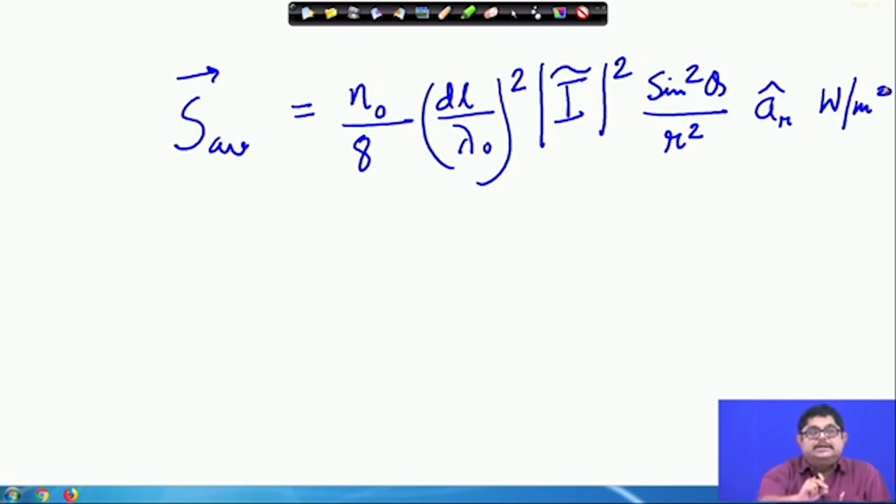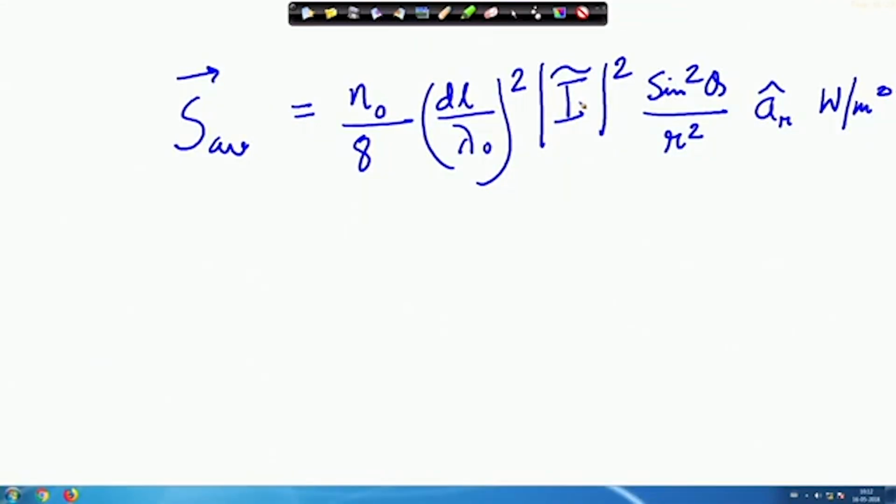Now, in practical cases, suppose I have a 1 centimeter antenna, but my wavelength is, let us say, 100 meters etcetera. So, that we can consider as infinitesimal. So, current elements are used. Then it depends obviously on the source strength, how much current I am giving.